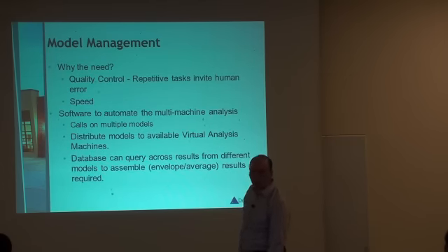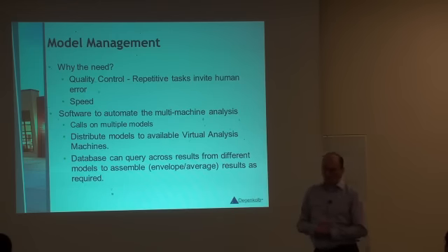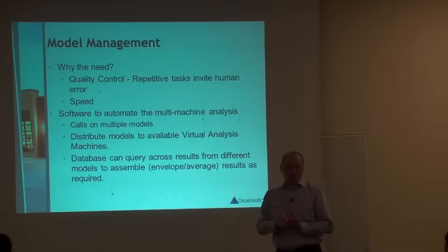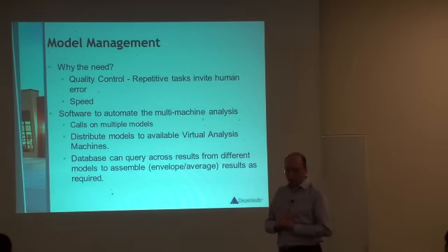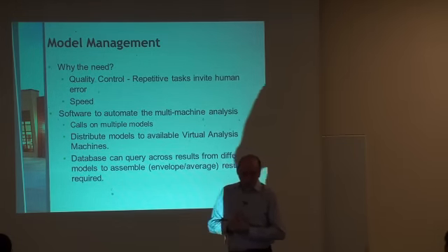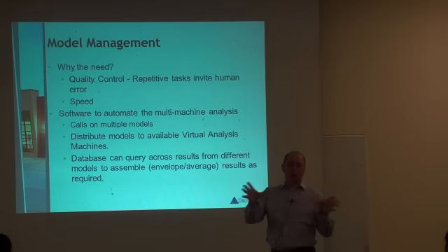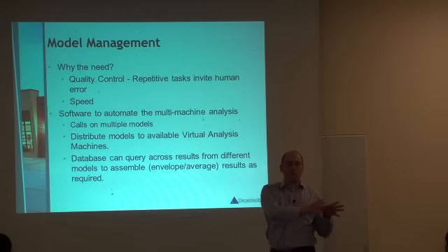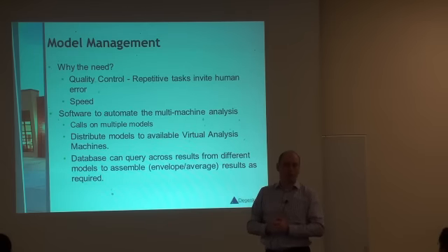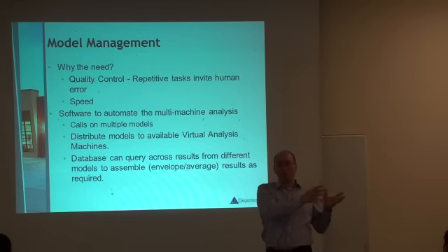We're developing specific model management tools. So very often we have the issue of running the same model many times, or variations of the same model many times. But we also have the problem of keeping multiple models in sync. So we usually have a nonlinear model in Perform or OpenSees. We have a linear model in ETABS because we need to design our gravity system somehow. And we may have other models. And you also have your Revit model, which you use to generate your CAD drawings. So keeping all of this in sync becomes a big problem.